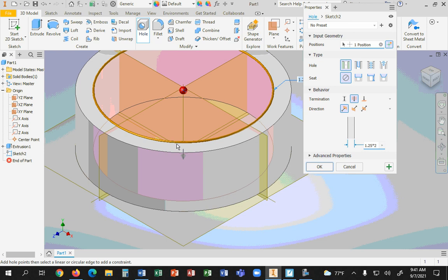The next question is, how deep does it go? Well, it's going to be a through hole. It's a simple hole. Is it going to be a tolerance hole? No, because I'm not putting a fastener through it. Is it a threaded type hole, a tapered hole, for example? No. Tapped hole, not tapered. Sorry, tapped hole is a threaded hole. It's not a threaded hole. It's not a tapered hole, which would be like a pipe fitting, an MPT. I'm not thinking about putting a thread in this thing. I just want a hole. Literally, a simple hole.